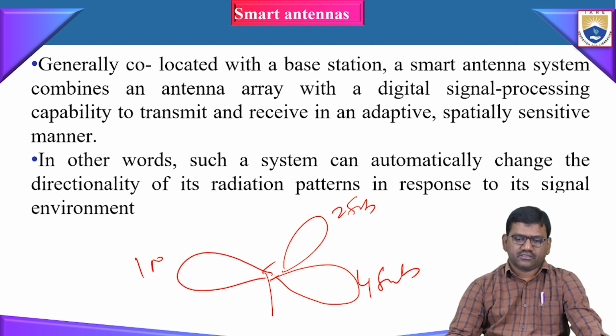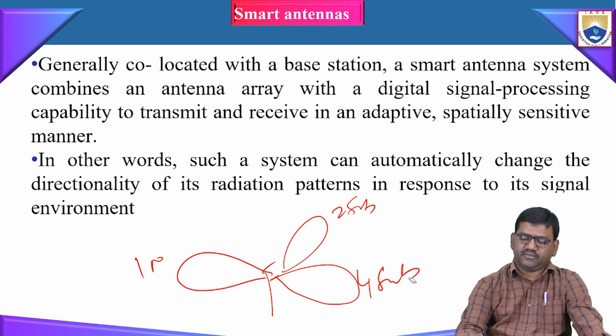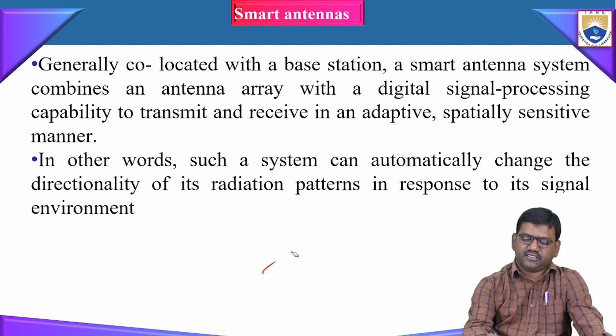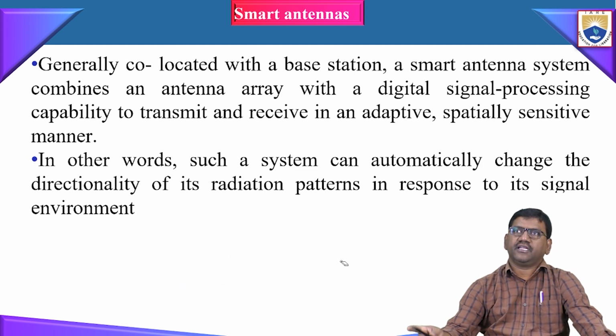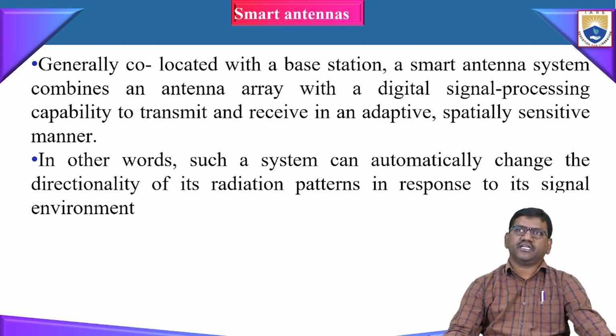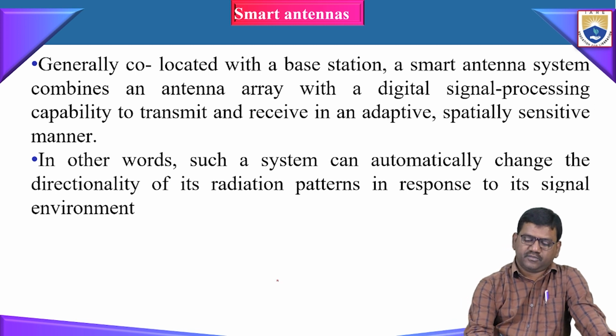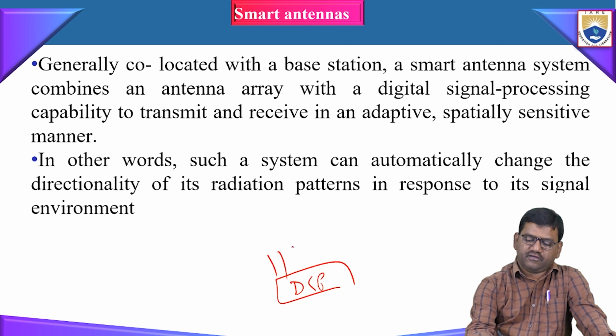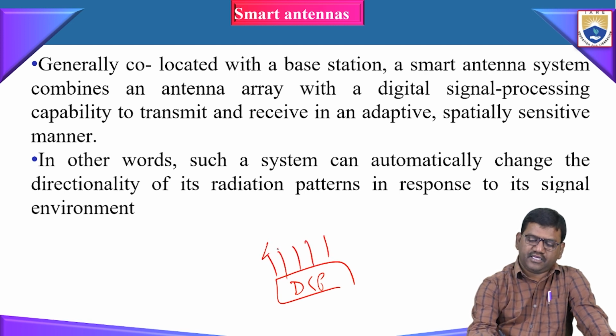direction. So the smart antenna is nothing but a system designed with an antenna array and a DSP processor. This DSP processor will decide to which direction the antenna elements must be automatically shifted. The phase shift of the antenna array depends upon the DSP. Suppose here there is a DSP unit. On this DSP unit, we are going to attach 5 antenna elements here.